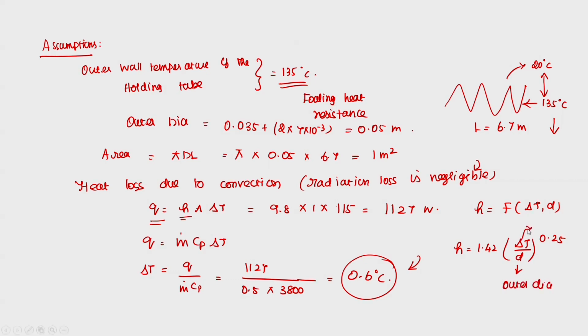So, del T is nothing but the temperature difference, that is 135 minus 20, and this is based on the turbulent flow characteristics and specific for the range of non-dimensional parameters. So, these kinds of correlations I would use to calculate the heat transfer coefficient and substitute here. So, everything comes from the fluid flow characteristics and product characteristics as well as the heat transfer characteristics of the product.